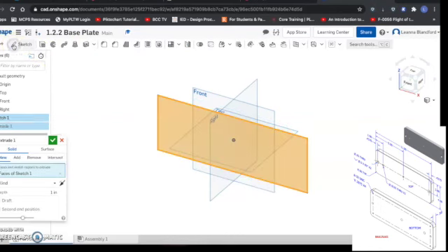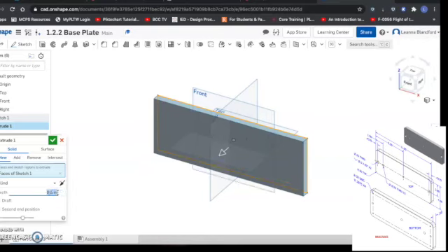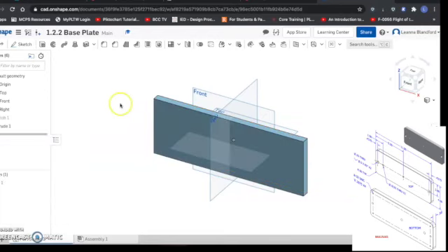And I am going to actually extrude this. And I should have hit my green check mark because I hit extrude, it auto ended my sketch. That's a little trick you can do. I don't recommend it because you can end up with some wonky outcomes from that. So the thickness of this overall rectangle is 0.5. So I'm going to change this to 0.5 in depth and hit the return key. Then I'm going to hit my green check mark.